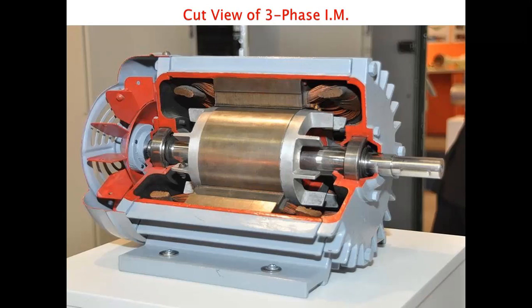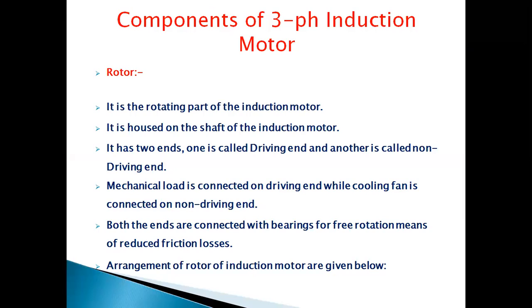After that, on the rotor, there are two types of induction motor. These are nothing but squirrel cage induction motor and the slip ring induction motor. So if there is a slip ring induction motor, you are supposed to use slip ring rotor and additional brushes to make the three-phase induction motor a slip ring type. And if we are using the squirrel cage motor, at that time there will be no need for these brushes and the slip rings. So here we can say about the rotor, it is the rotating part, it is housed on the shaft of induction motor and it will be inside the stator.